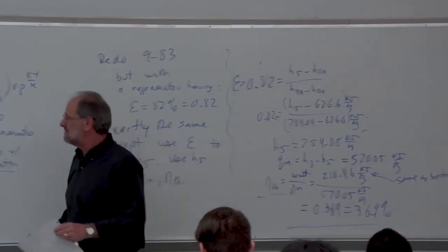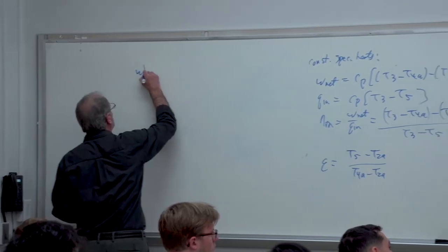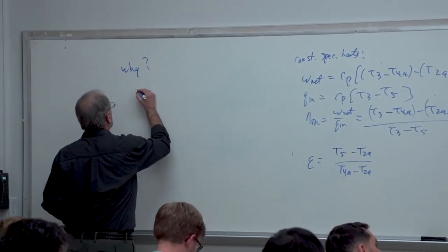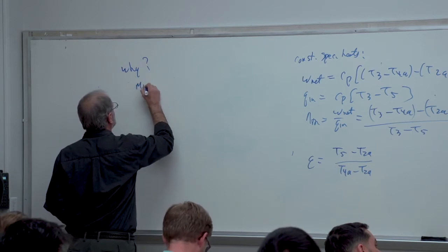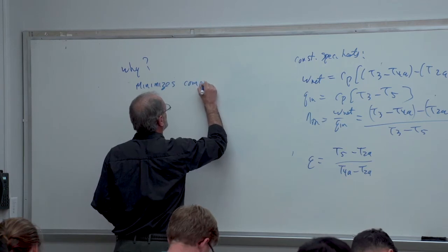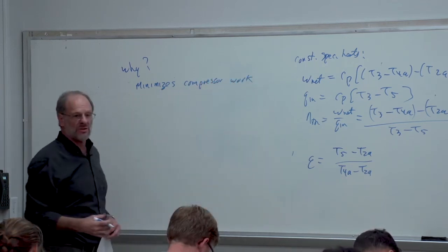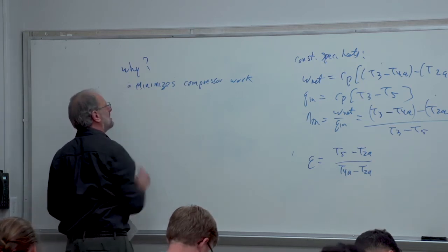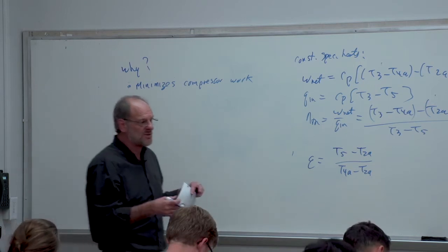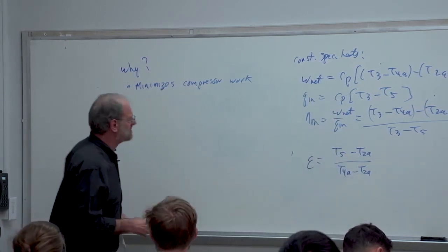Now, why do we need it? Well, again, I'm just going to write down what I'd summarized before. This allows us to minimize, so this minimizes the compressor work. That's certainly one advantage to this particular process. Okay? I mean, even though we need 2 separate compressors, the total amount of work combined is going to be less than it would if we just had a single compressor.